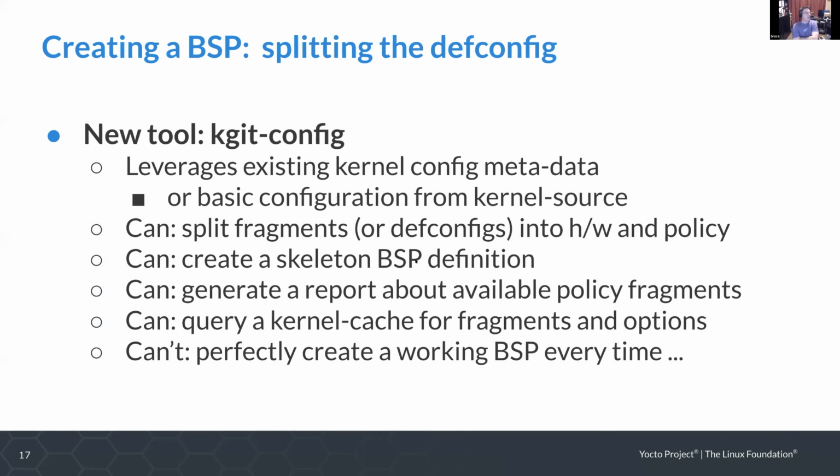So what if you wanted to, again, like I said, not fight with the defconfig, or not track the defconfig, or you wanted to freeze some configuration, and you don't want to start from that in-tree defconfig and only add to it and fight with the selects and deletes? If you don't want to do that, you might want to be able to split the defconfig and pull out the hardware options and just set the software options yourself.